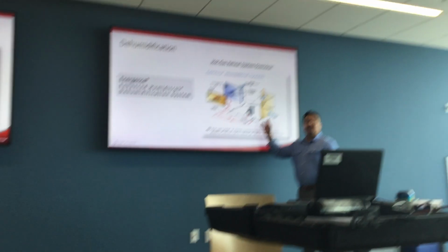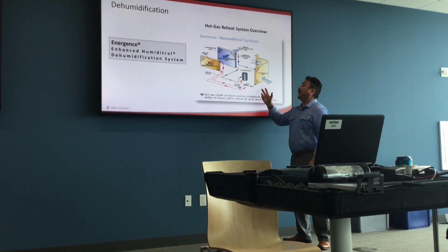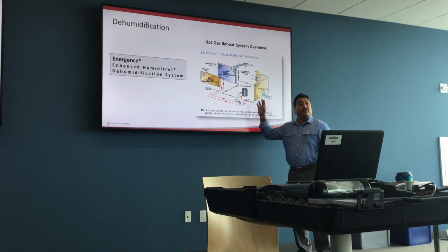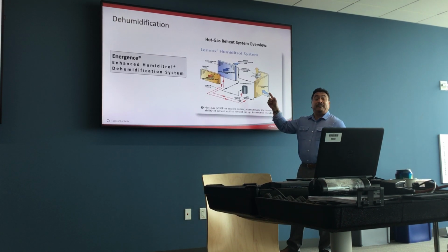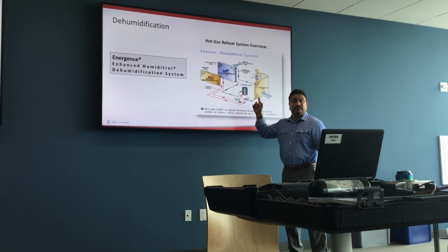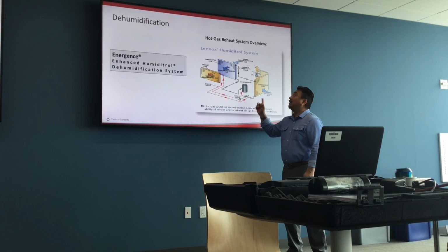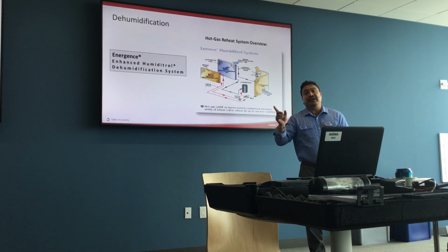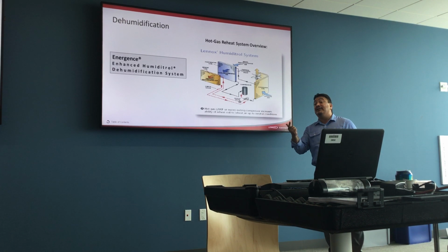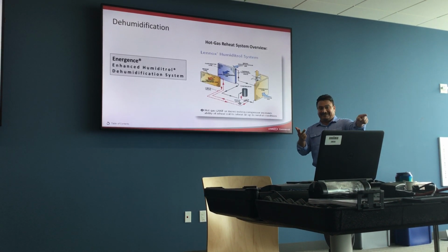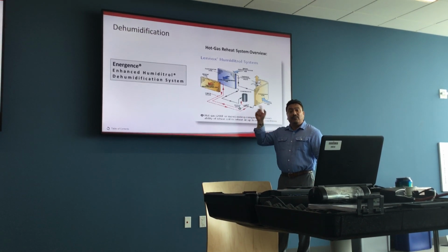So, the purpose of the condenser is to do what? Reject heat. Perfect, okay? Obviously, our compressor is the heart of our system, creating the pressure differentials needed to pump the refrigerant through the entire system, right? Expansion valve, what's the purpose of that? Regulation. Regulate pressure. Change the state of the refrigerant from liquid to a gas, okay? When we change the state of the refrigerant, we're also changing its pressure. So it's no longer a subcooled, high-pressure liquid, it becomes a what? Low temperature, low pressure, yeah. Gas, right? And when it enters the evaporator, what are we doing at the evaporator?